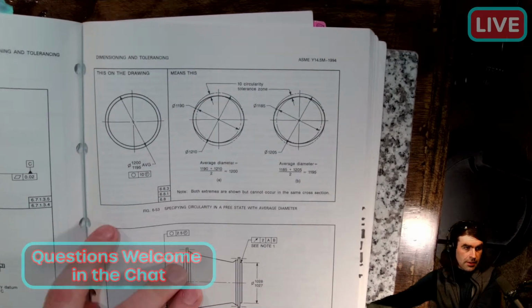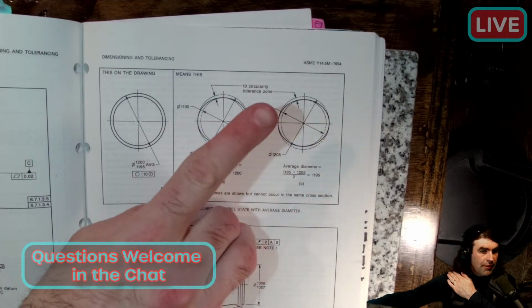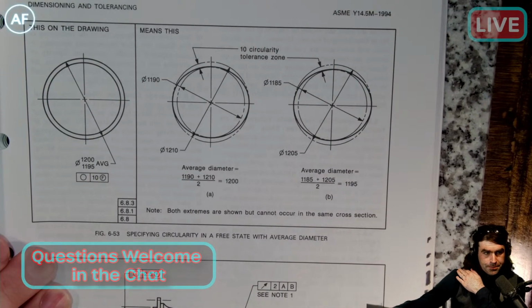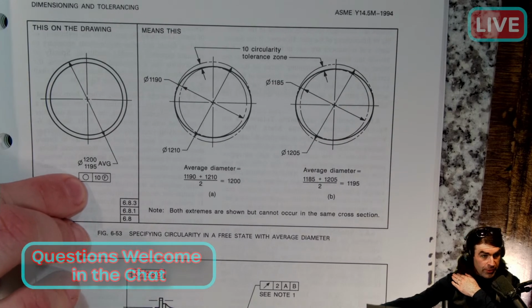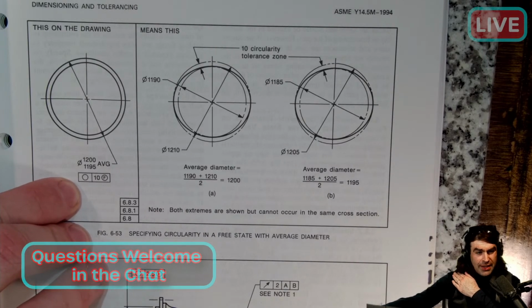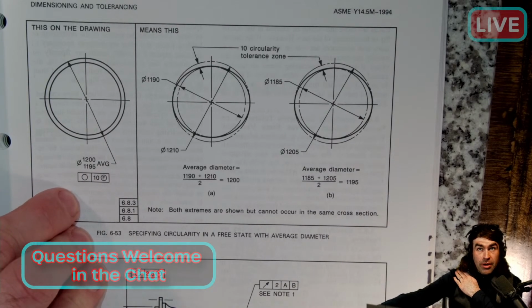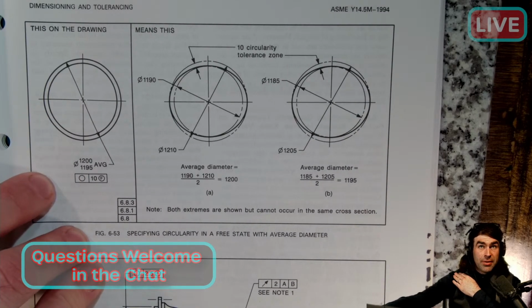So here's average diameter in Y14.5M-1994. It's not the most current version, but I don't think this has changed at all. So yeah, you're right. The circularity is attached to the dimension. It's a little weird in this case, right? It still applies to the surface, so we're not controlling an axis or anything. I'm no expert on average diameter, but I think you could just point this with a leader and it would mean the same thing.